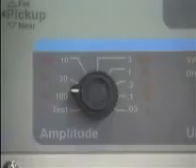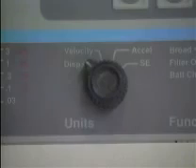In general, the highest range for the amplitude meter is selected to begin a measurement. If the amplitude indication is too low to read accurately, the next lower range can be selected. The next step is to select the vibration characteristic to be monitored. Velocity is generally checked first, since it provides useful information about vibration over a wide range of frequencies.